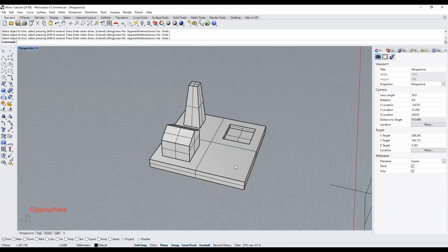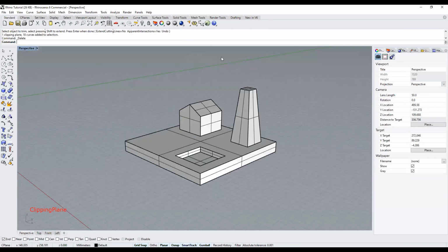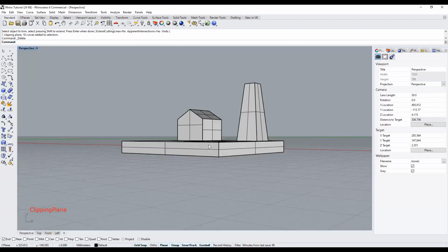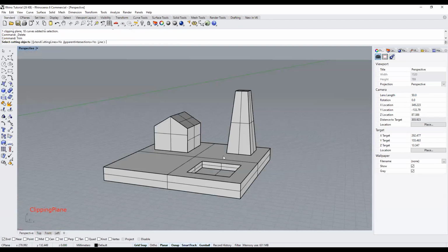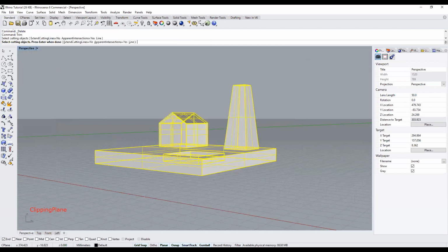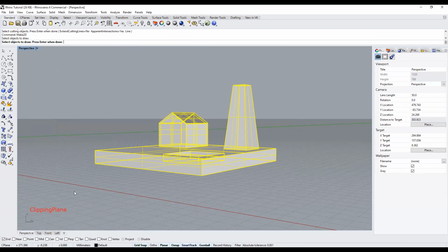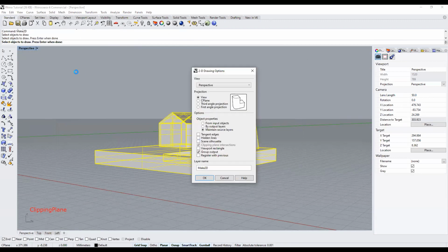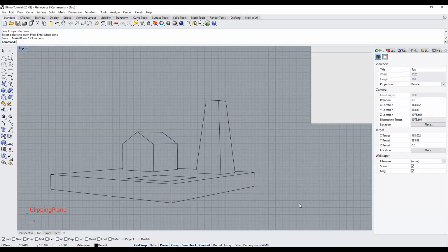As for the renders, like I said, for Make2D, it copies exactly what you have from that view. So I want this view, I want an outline of this. Select everything, make 2D. Enter, okay. And it'll create an outline of it.